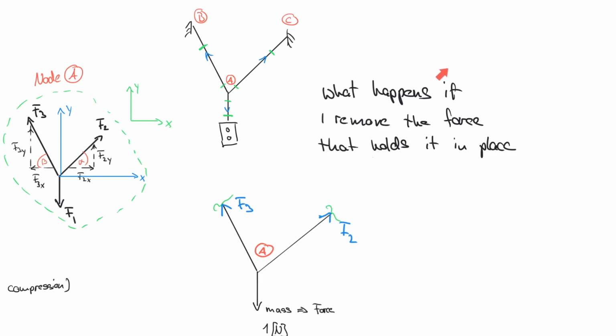And this is the real concept that we're going to do so many times when we start actually calculating support reaction, like how much force is acting here on the wall, and so on and so forth. We will first remove the forces that we don't know, and then we will calculate or analyze how much it takes to bring it back into equilibrium. And that is an important concept.